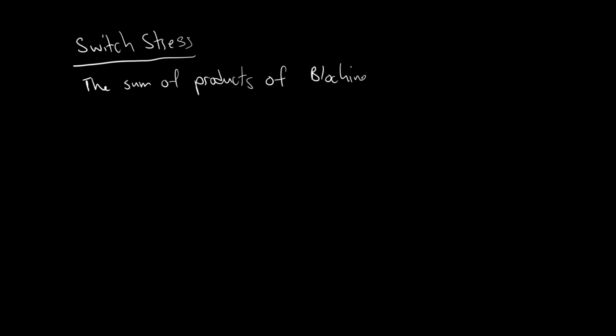Switch stress. You can define it in a few different ways, but the way I'll define it is the product, or the sum of the products, of blocking voltage and RMS current of active switches.